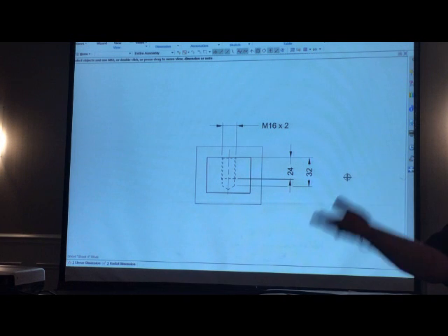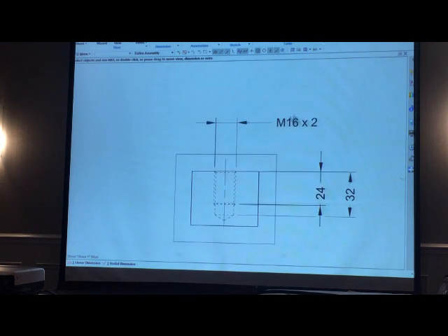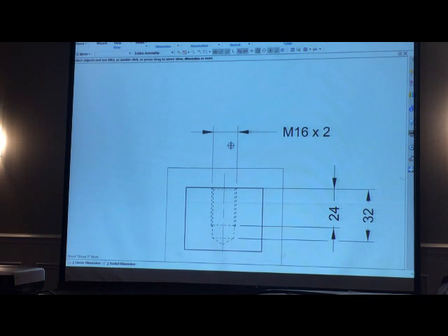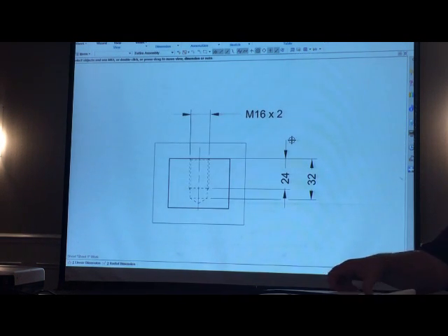It's just faster. It's quicker. If this is your normal way of working, fine. You can now dimension your holes this way. Saves you a couple extra steps. And you can still use the annotation call out for the linear part, for the size part. So you don't have to do a combination of things.